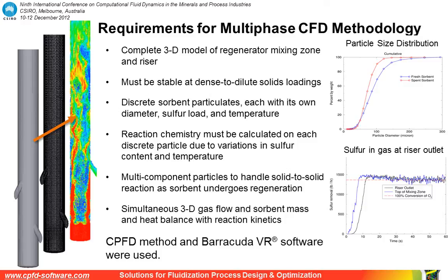The requirement for being able to model this case is that you would need to have a CFD methodology that was capable of modeling dense to dilute solids loadings, and also to capture discrete sorbent particulates, each with its own diameter, sulfur load, and temperature, and track how those change as the reactions occur.